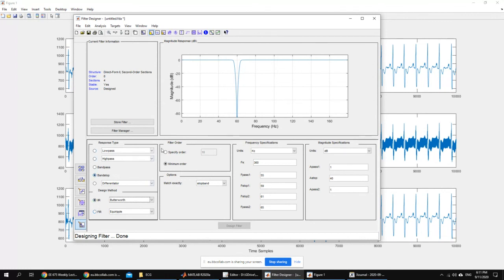So basically what we did now was we used something that has ECG in it. We wanted a signal that has ECG in it because we'd like to know the effect of the filter on our ECG signal. For example, if I said that I'm going to use a low-pass filter with a cutoff frequency of 50, some people might think that the ECG might have more frequencies than 50.